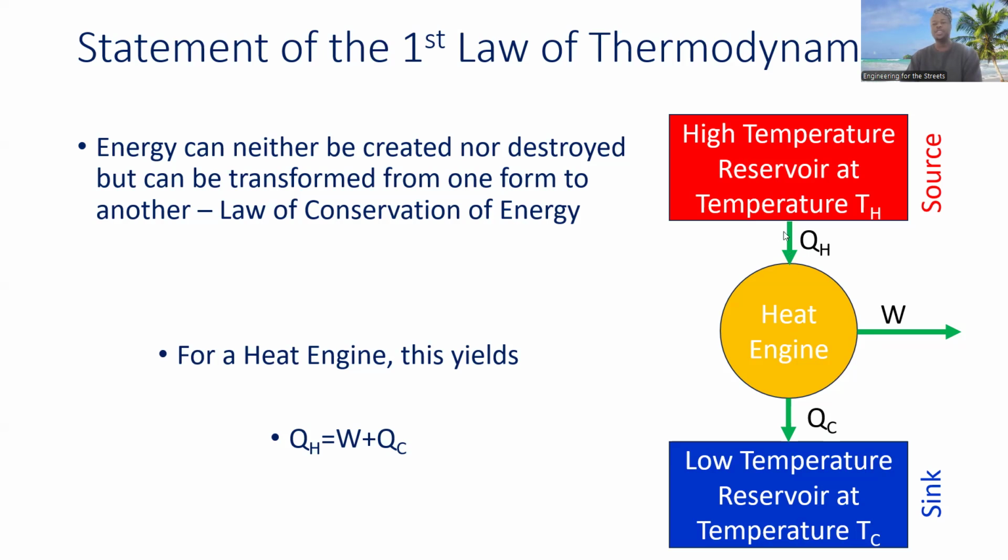So if QH is the heat it receives from the high temperature reservoir, W is the work done by the heat engine on its surroundings, and QC is the heat rejected by the heat engine to its surroundings, then the sum total of all the energies going into the heat engine is equal to the sum total of all the energies flowing out of the heat engine.